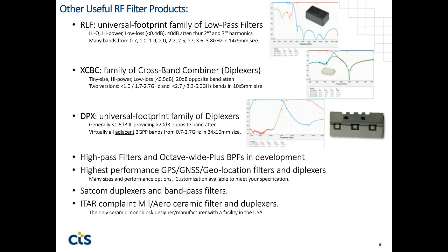So the average power into the filter is going to be higher than what comes out because you have filter losses. And then there's peak modulated power, and in many instances for a monoblock, the peak modulated power is in fact the limiting factor. So even though we might be fine with average power, we might even be able to accommodate more average power than we admit on our data sheets.